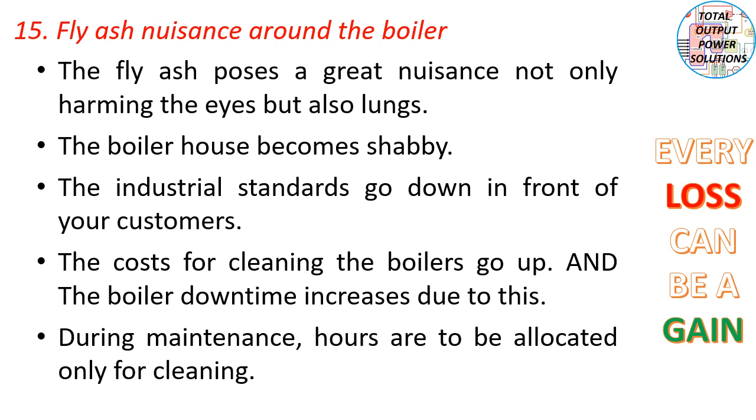The most important is again the fly ash nuisance around the boiler. The fly ash poses a great nuisance, harming not only the eyes but also the lungs. The boiler house becomes shabby. The industrial standards go down in front of your customers. The cost for cleaning the boilers goes up and the boiler downtime increases due to this. During maintenance, hours are to be allocated only for cleaning. So these are all the effects of excess air ingress in the boiler.